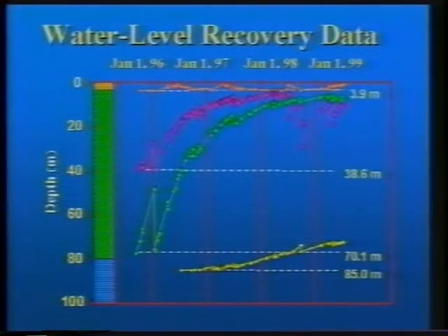The second point is we needed hydraulic gradients. We obtained those from our water level data. As I mentioned earlier, our water level data below 30 meters for all our piezometers still have not reached equilibrium. The ones above have. These are representative recovery data for the piezometers. Again, the spikes are the result of sampling. What you can notice is the very shallow one, the brown one, is in the oxidized and fractured till, and you can see dynamic flow up there. Every spring the water level rises to at or near ground surface, then drops throughout the remainder of the year. This is a result of the spring recharge. Waters in this oxidized and fractured zone are all tritiated. All waters collected below that are non-tritiated, below detect.